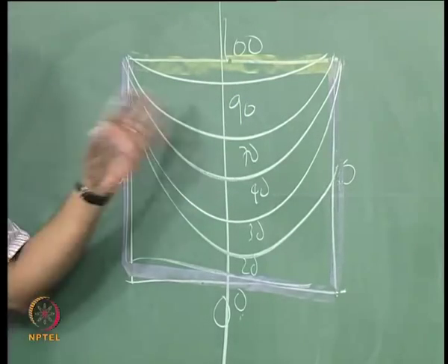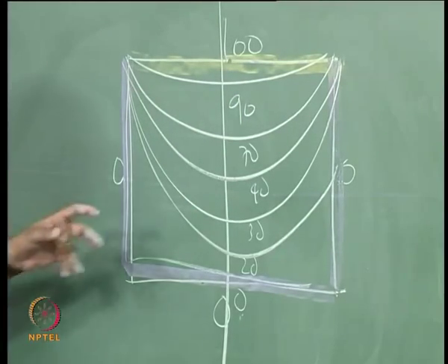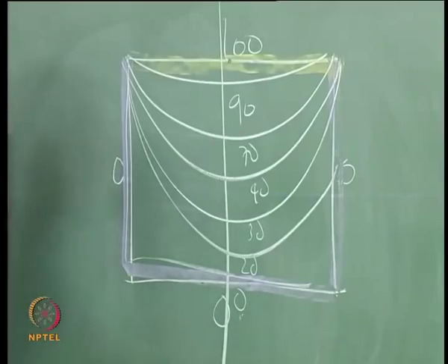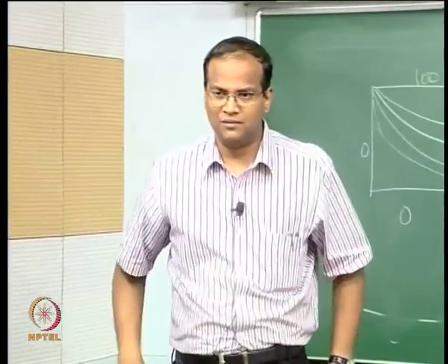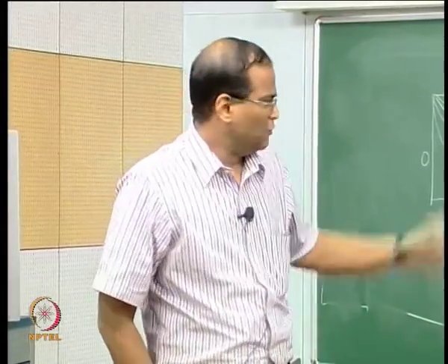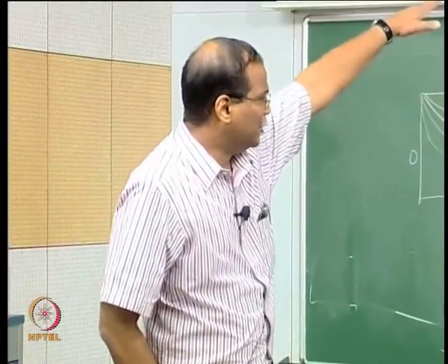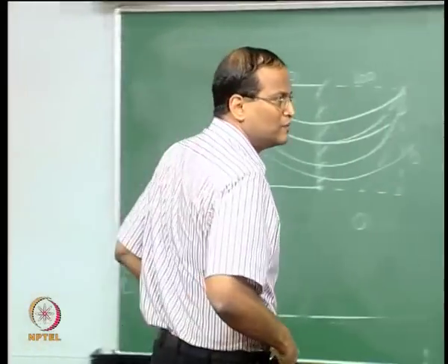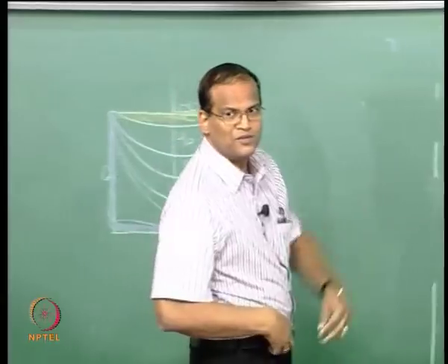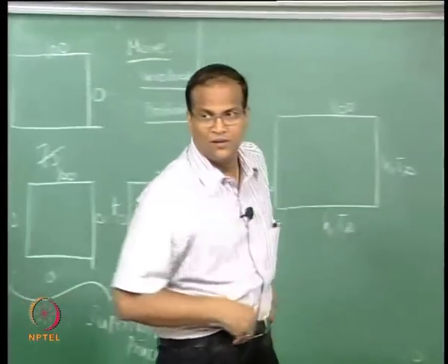So when you read an isotherm after you solve a problem and you plot it, it must be intuitively apparent that there is no violation of physics in the problem. This is the way to interpret. It should be symmetric about x and the temperature must decrease exponentially from the top to the bottom. In fact our solution confirms this, the numerical solution confirms this.